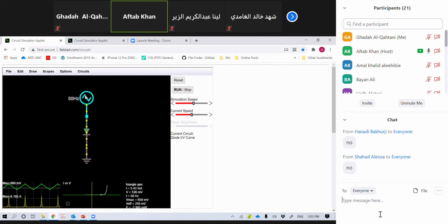So when it is operating, you see how it is working, this VI characteristic. In order to understand this, look here. We applied a triangular wave here. See, this is the triangular wave. So how is it happening? See, the voltage is going down, and this dot corresponds to the voltage, showing how the voltage is increasing. You can see that the voltage is increasing, but there is no current. But as it reaches this point, how much is the voltage at that time? 0.7. You can see this is in millivolt, 721.63 millivolt, that is, 0.7 volts.